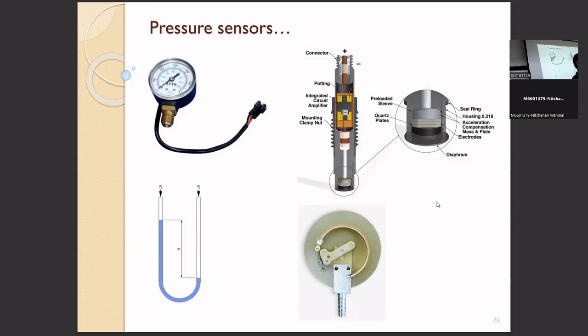When you have to open some property, you will open the property of the air. In the database, it is represented in absolute pressure. But from the equipment, it is gauge pressure. Okay, it's very, very important. You have to consider this.